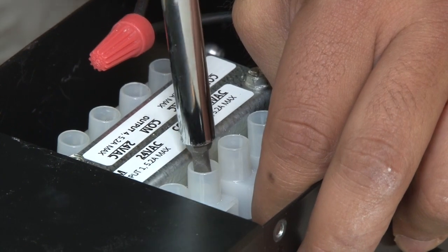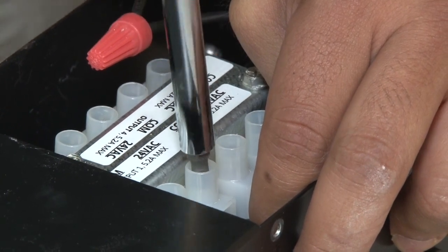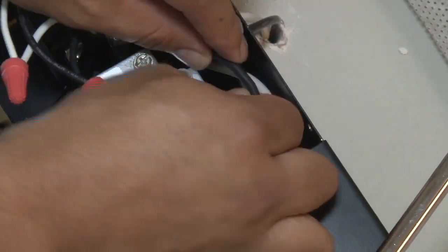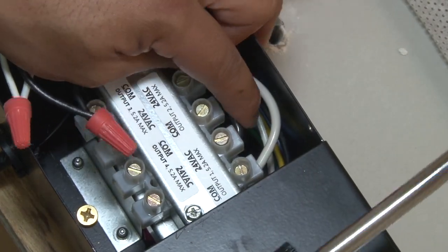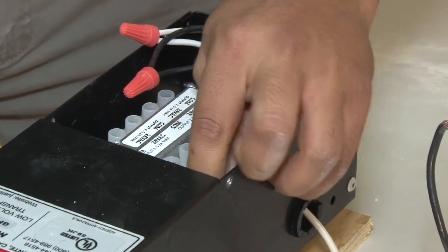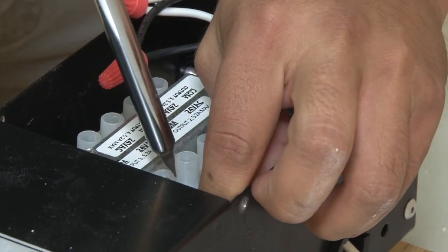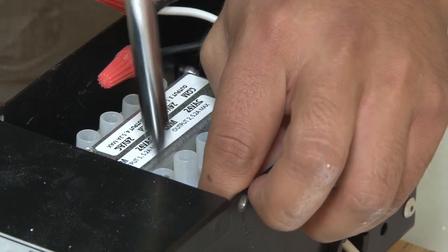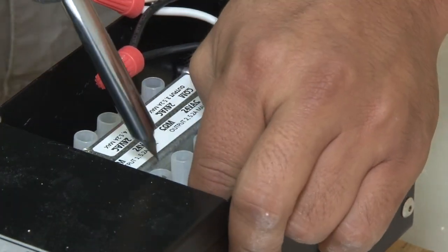Ensure that all wiring is run through the UL-listed conduits. Connect the heat supply wires to the transformer load terminals. Ensure that the heat strip is connected to both a common and 24-volt AC terminal. Be sure that all 24-volt AC terminals are wired with the same color, and that the common terminals are wired with a contrasting color wire.